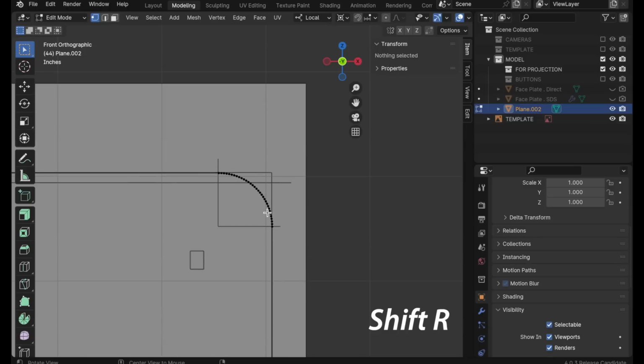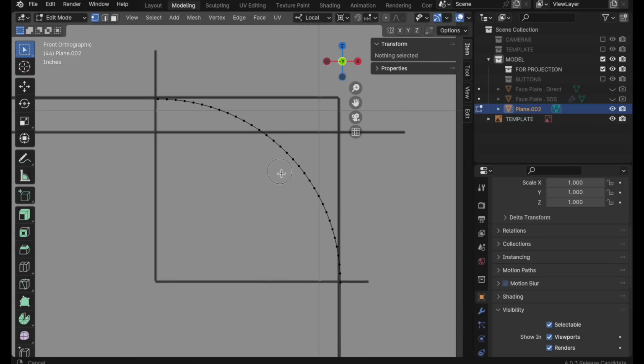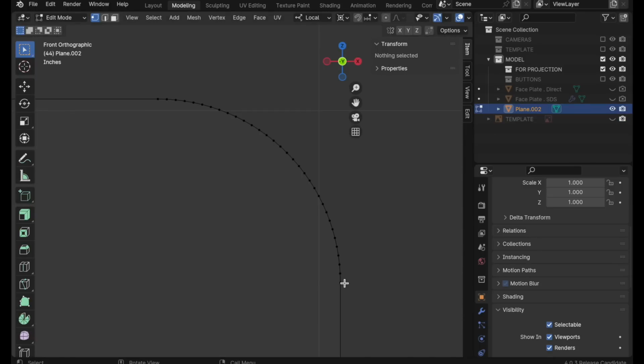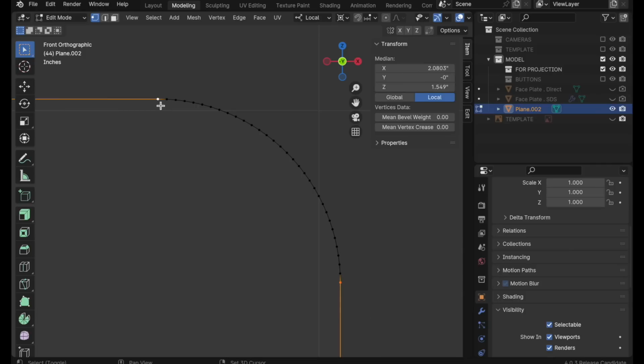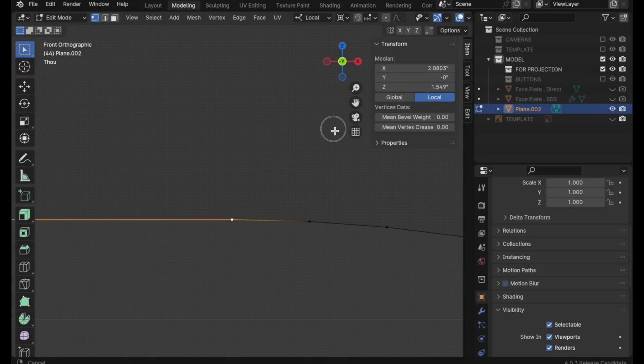The next thing that we want to do is add a bounding edge. Let me turn off the template temporarily. We want a bounding edge or vertex past the curvature area. If we zoom way in, we can see this angling and the faceting of the angles here. This angle comes right up to this very long straight area, and we don't want surface normal shading to pass this area.